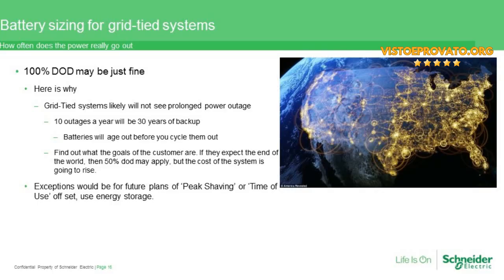When we talk about which product from Schneider, if it's the Connext SW or the XW Plus, then we have to look at when we're going to be using it. So one thing to note is that the Connext SW is not a grid tie inverter, but is a really nice inverter for, say, a small system of 3 to 4 kW of solar, and you need to AC couple to that. So that's really where the SW shines, and cost per watt is very, very reasonable. With the XW Plus, of course, you can do the whole AC coupling or do grid tie with battery backup from the very beginning. And again, this makes the most sense.